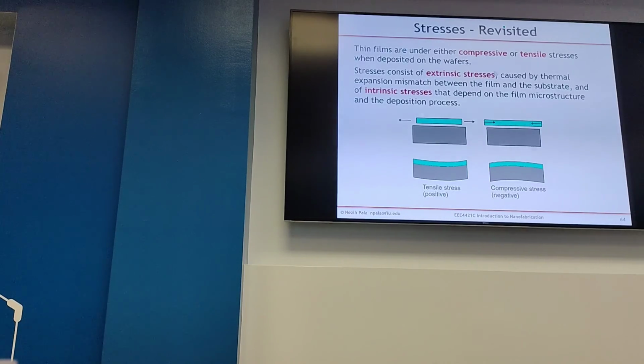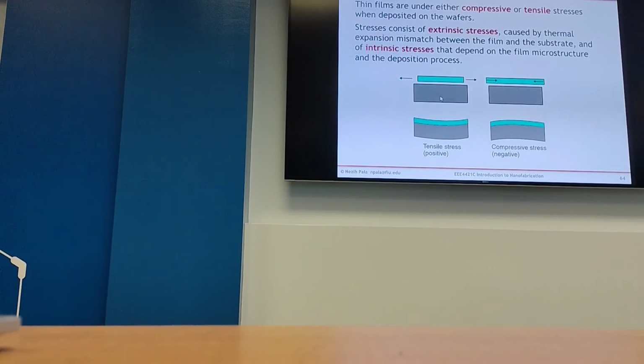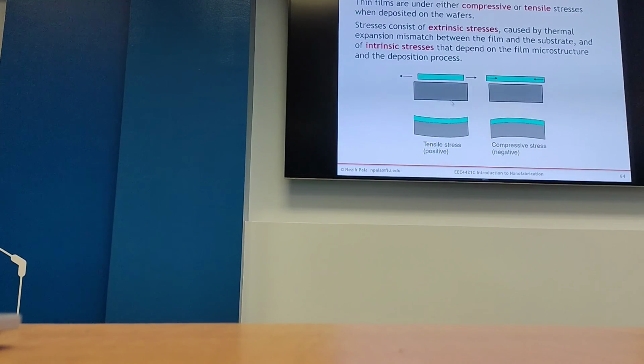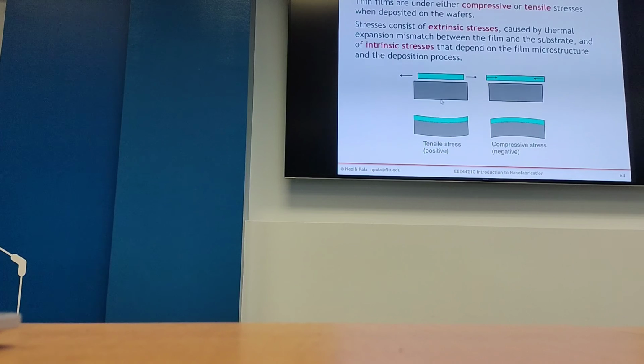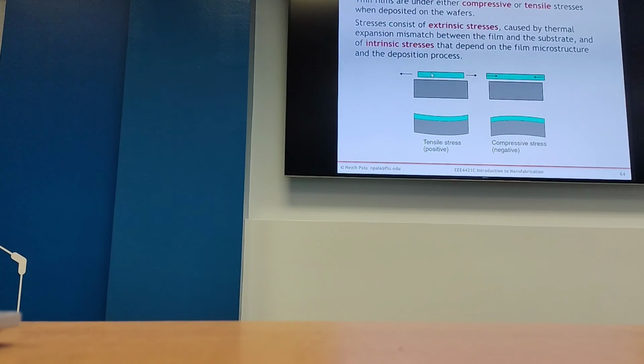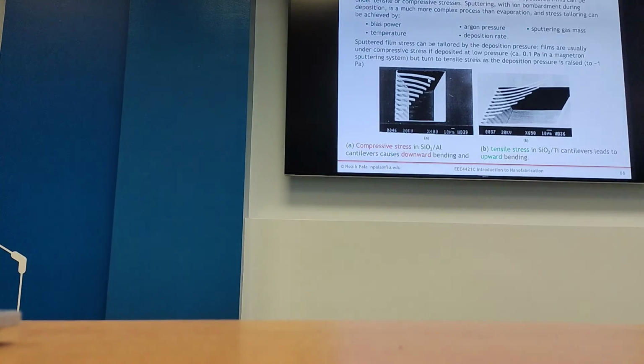Coming back to stress, when you deposit metals, thin metal films on thin dielectrics, you may end up with either tensile or compressive stress. With tensile stress, you have a larger atomic distance for the overlayer, so it will push the atoms. You will end up with upward bending, and for compressive stress, you will have lower, negative bending. As you see here,